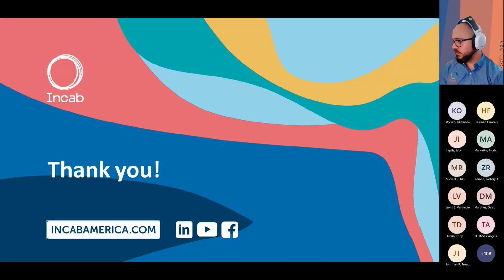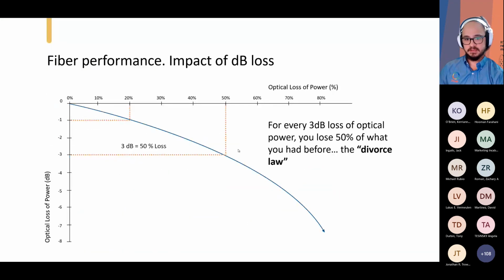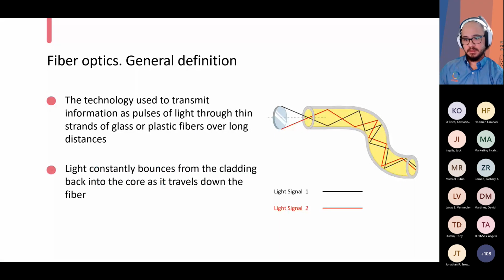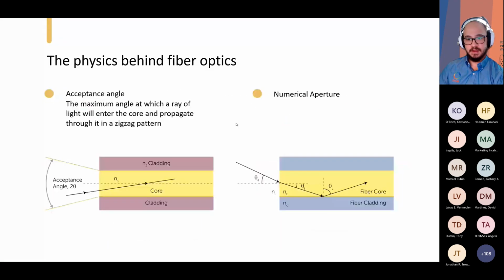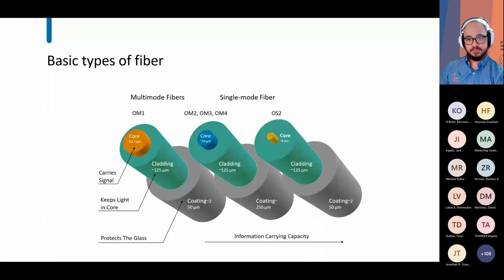Frederick, you asked, I thought multi-mode fiber had light bouncing from side to side, but single mode did not. Apparently that is incorrect. Both fibers propagate in the same manner. Multi-mode just has much more room in the fiber. The core of the multi-mode fiber is significantly larger than the core of the single mode, so you're able to put multiple wavelengths in the multi-mode, whereas for single mode you're just using one. They both propagate in the same method; multi-mode is just able to do it with more than one light wavelength at the same time.